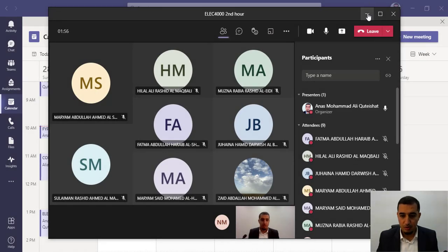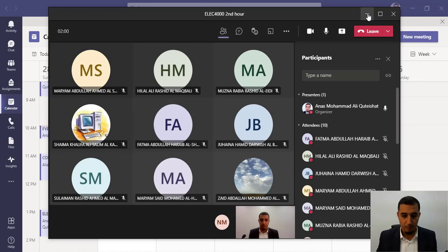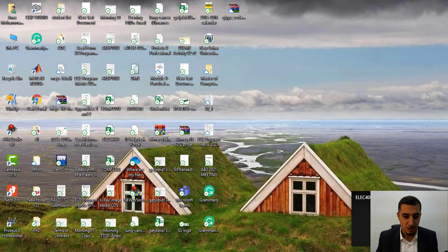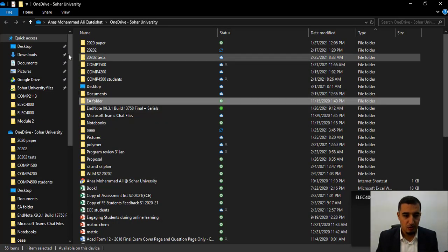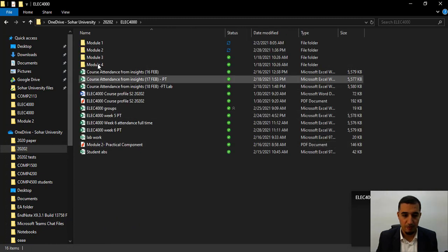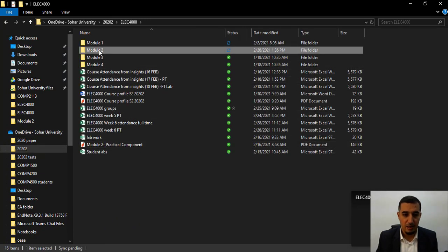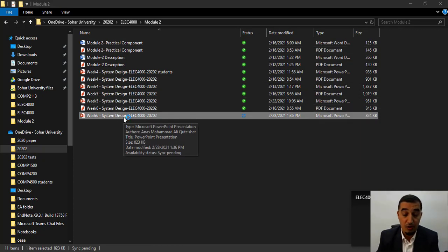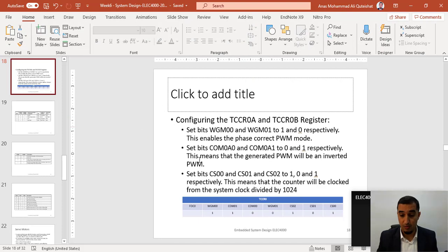So today we will start talking about pulse width modulation and how it is used to control the servo motor. Now, a servo motor is a special type of motor. These motors are controlled by varying the angle. They are controlled by varying the duty cycle at a certain frequency.